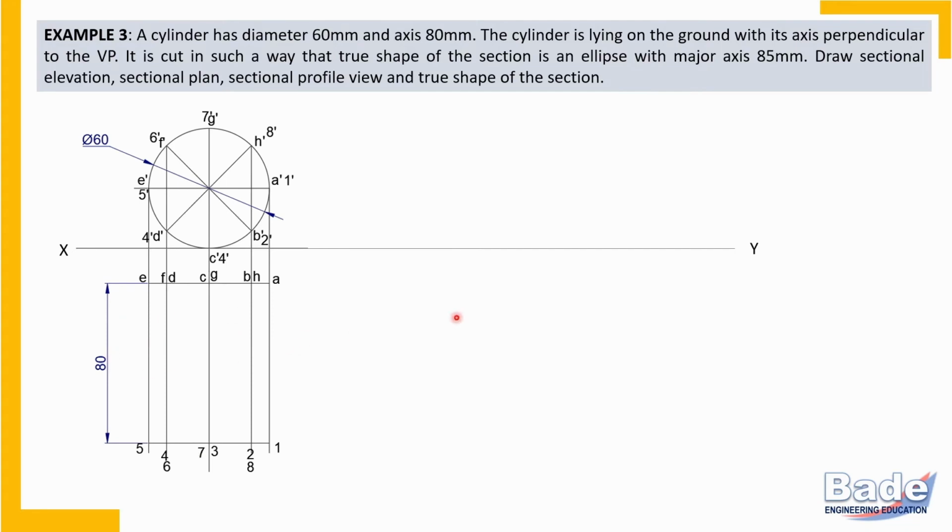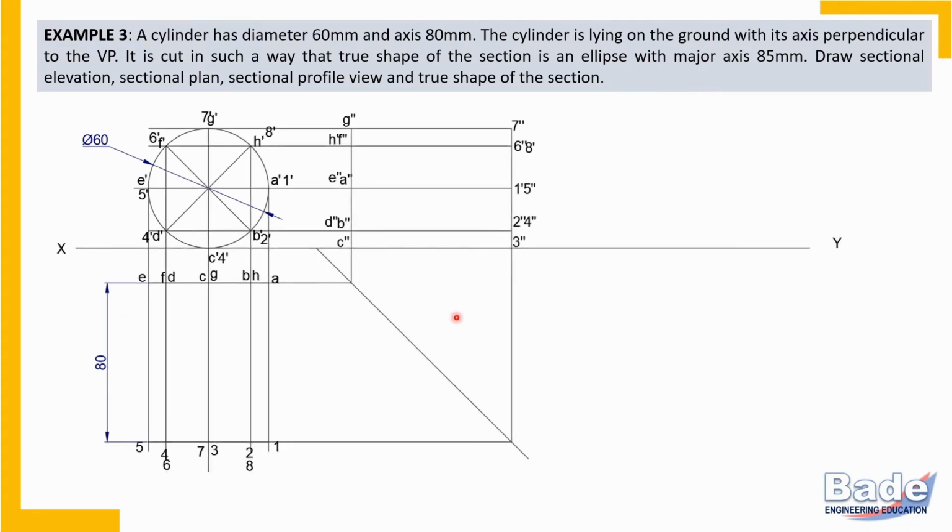Now since we are asked side view, we should complete the side view also. So project all 16 base corners and numbered corners here. These are of course not sharp corners. So this is how all generators and all those 8 plus 8, 16 labeled points are in the side view also. So this is the position of object.